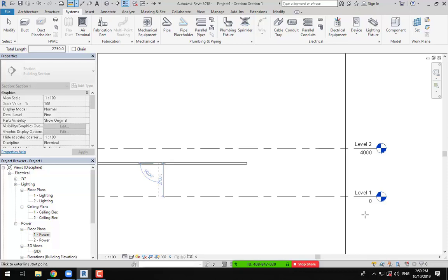This step we didn't reach. But this template, to make these floor plans, he needed to put these levels here, so you can create these cable trays. If there is no reference level here, can you create this cable tray? No, you can't create this cable tray if there are no levels. You must create levels so you are able to create a cable tray, duct, any discipline, or any system. Okay.